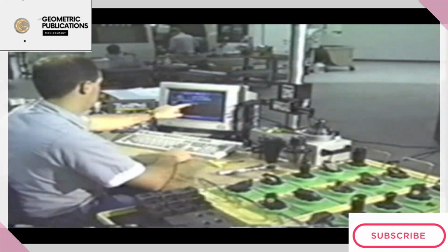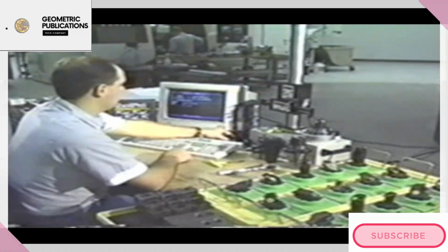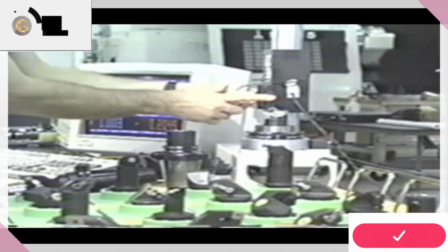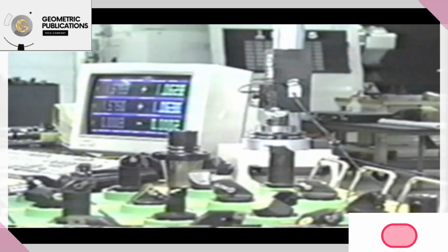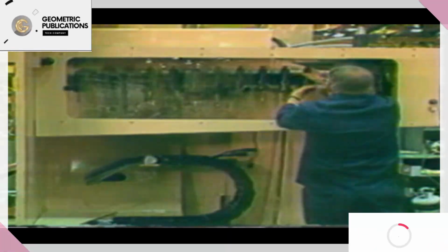The second accessory is the tool presetting machine. It enables the machinist or tool room technician to accurately assemble tools and tool holders to the length and diameter assigned in the NC part program before placement in machining center tool storage.